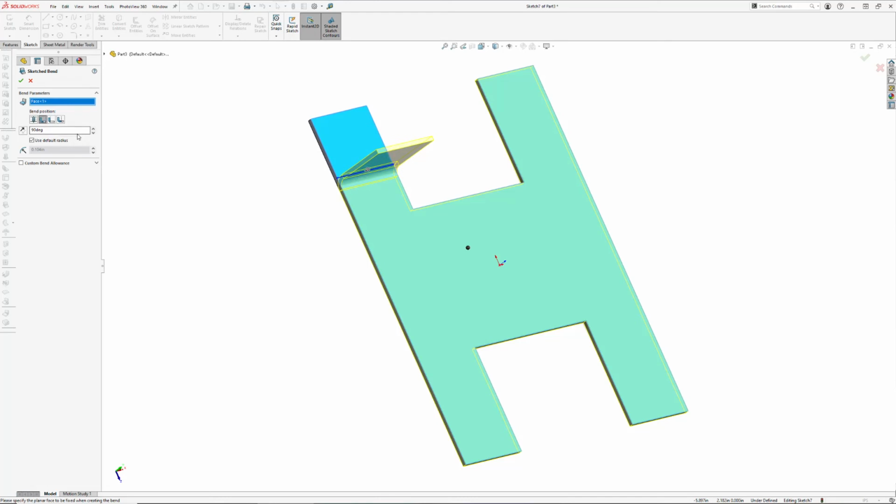Do you want it to represent the outside of your bend, the inside, or do you want the bend to go completely to the outside of that line? Okay, so you have those four options. Now, here, you can flip your angle, or your direction of bend, I should say. So if you want to go down, you can select that. We'll go ahead and leave it as going up. You can change your angle, 45 degrees, whatever you want to put in there. Okay, it'll change that. We're going to go ahead and leave it at 90 though for this.